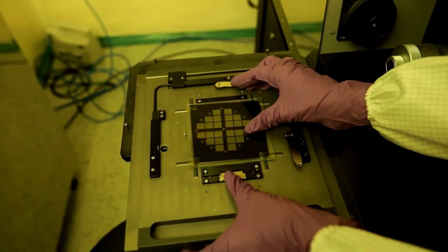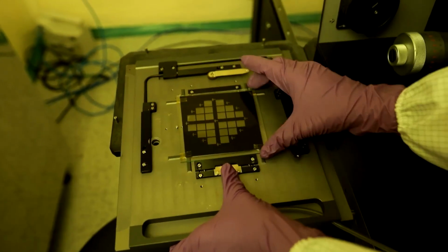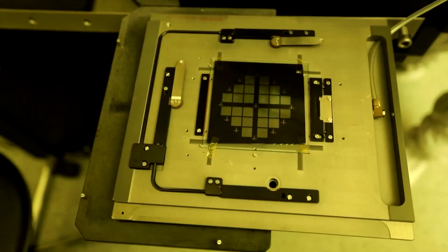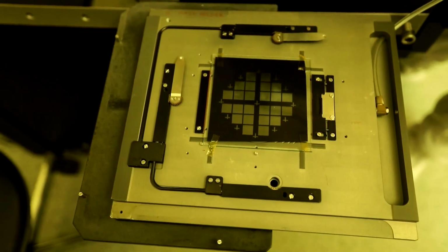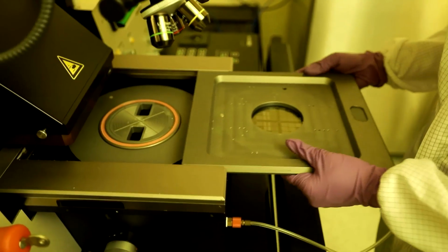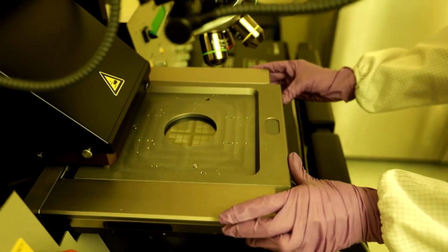Release or pull back the mechanical lock and keep the clean photomask in the slot of this holder with chromium coated side facing upward. During exposure, the side will be making contact with the sample. Press Enter to allow the vacuum to hold the mask plate. Keep back the mask plate holder in its slot and press Change Mask to lock the mask holder in its position.